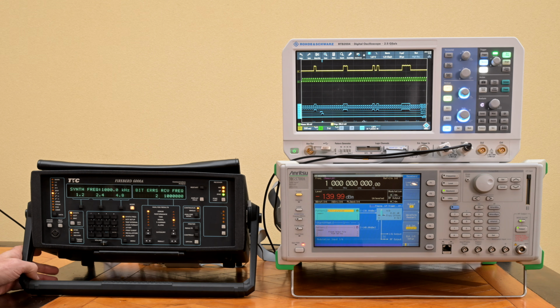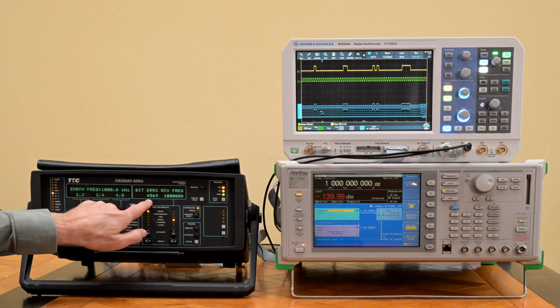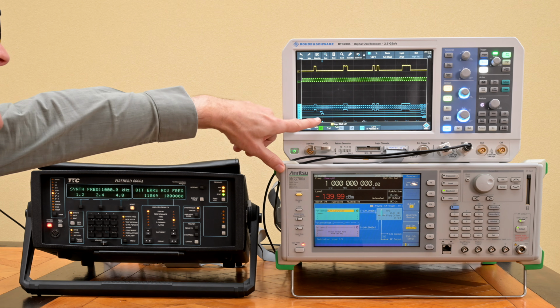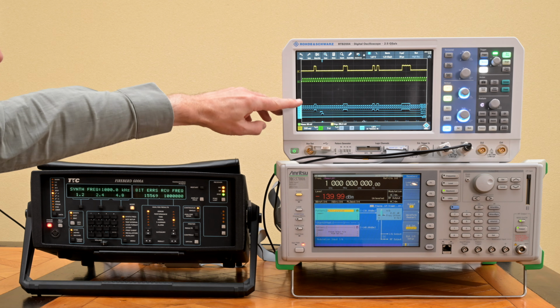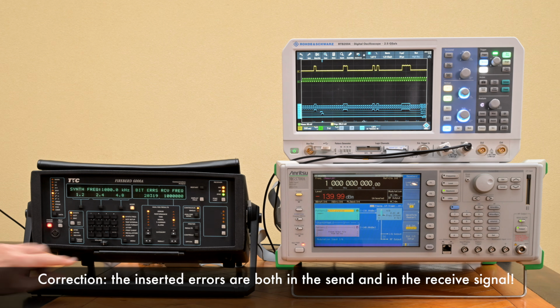Now let me try to see if we generate a little bit more errors, and once I use again the error insert button, but I keep it pressed, it will continue to insert errors at a predefined rate. So let's do that. I'm getting a lot of beeping, I'm getting a lot of bit errors right over here. I'm in the menu that is showing me bit errors. And now if we look on the oscilloscope, once in a while we do see errors coming in here. We do see differences between the send and the receive data signal, and we see the error bit basically coming in here.